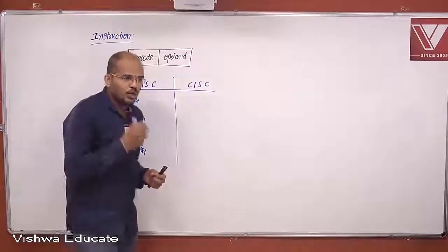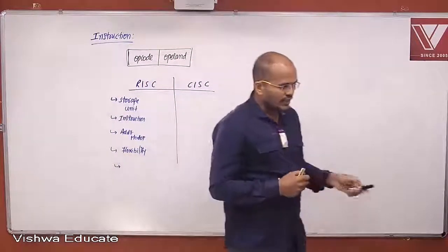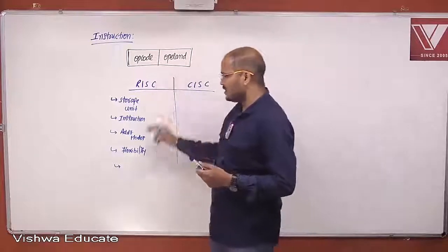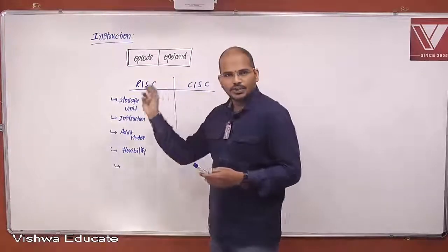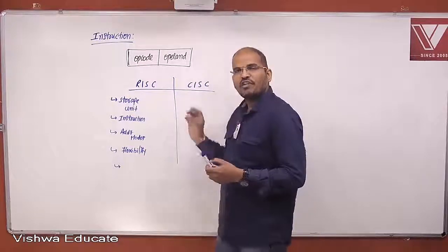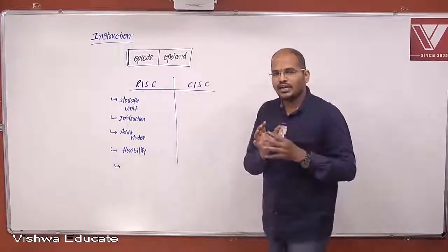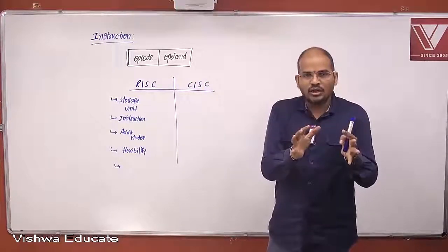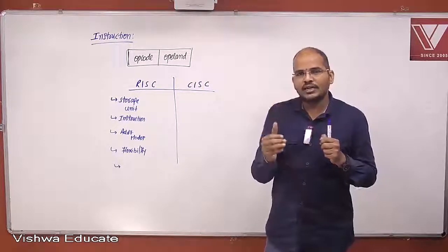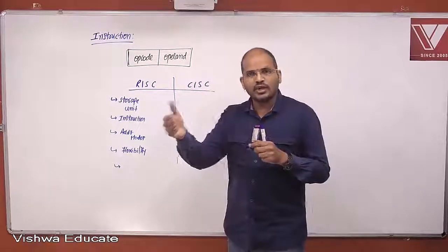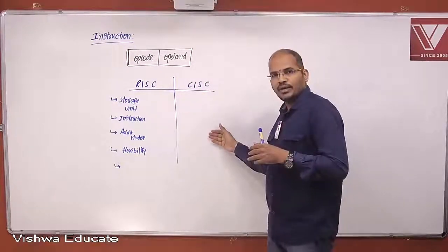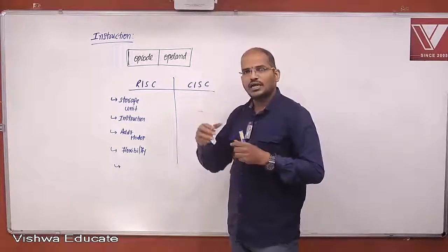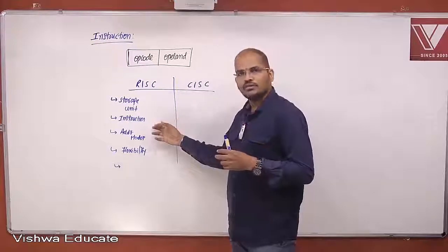And coming to the speed of operation, the thing that makes RISC advantageous is, as RISC deals with registers, this has got a better speed compared to CISC based machines. Why better speed? Because as the data is found in registers and registers are a part of the processor, it can handle the data found in registers faster when compared to the memory based things here. So compared to CISC, the speed of processing is a little faster in RISC based machines.